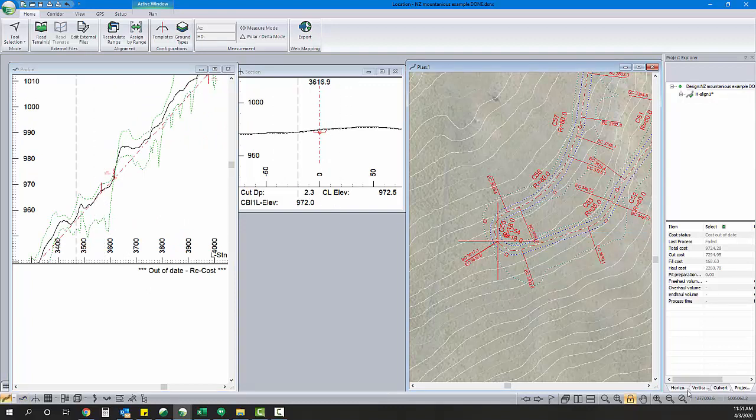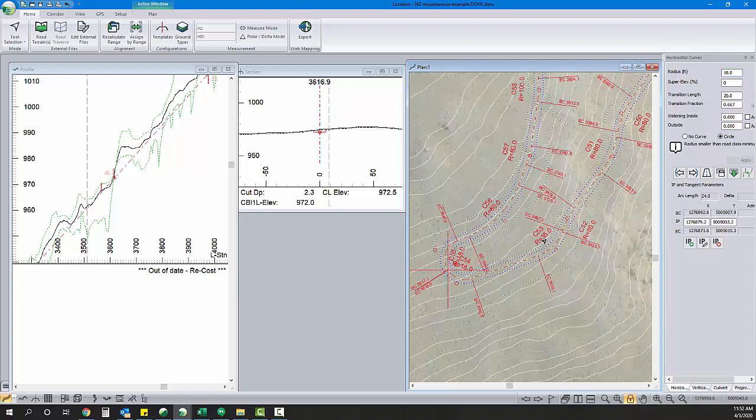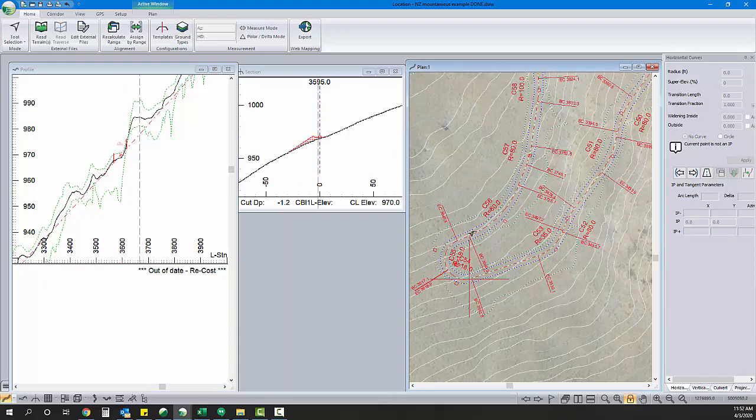For adjusting the curves, we set our radius. So I've got an 18-meter radius curve for a switchback. So that's also pretty normal. You have a reduced design speed through your switchbacks, more focused on getting the trucks around it rather than maintaining your design speed of whatever we have. Here we've got a lot of R35s, so 35-meter radius curves, so that the rest of the road's probably around a 30 km/h design speed. Yeah, so that's the one switchback.